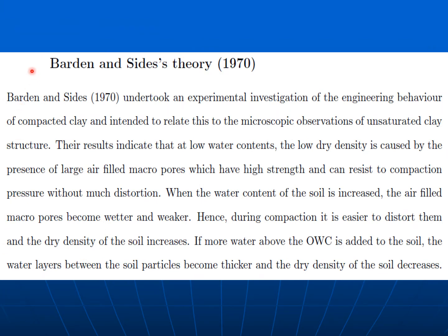Then look at the Borden and Sides theory, which came in 1970. Borden and Sides undertook an experimental investigation of the engineering behavior of compacted clay and intended to relate this to the microscopic observations of unsaturated clay structure. Their results indicate that at low water contents, the low dry density is caused by the presence of large air-filled macropores which have high strength and can resist to compaction pressure without much distortion.